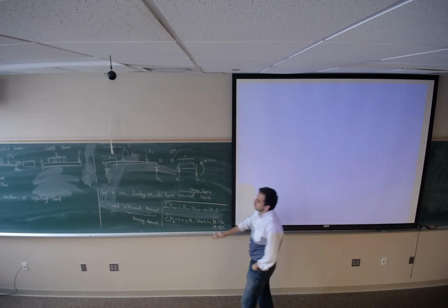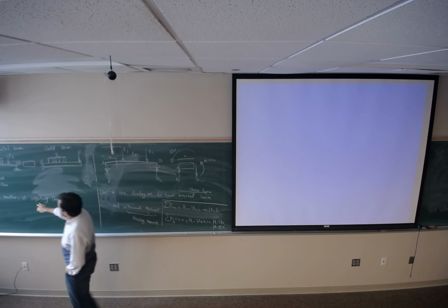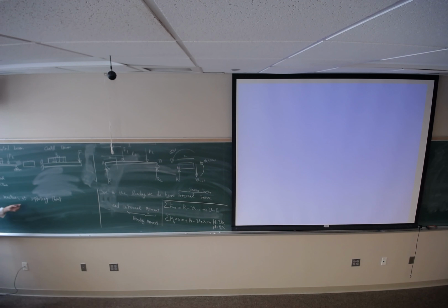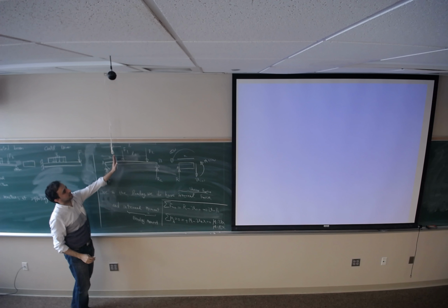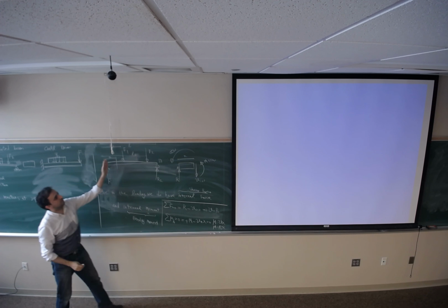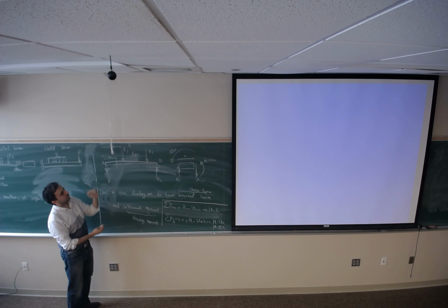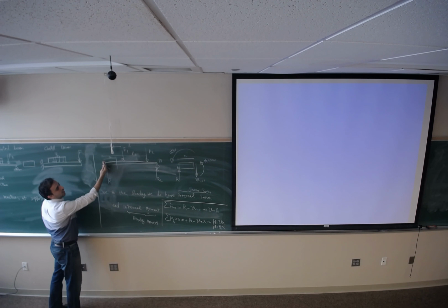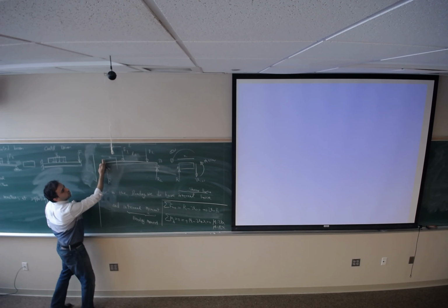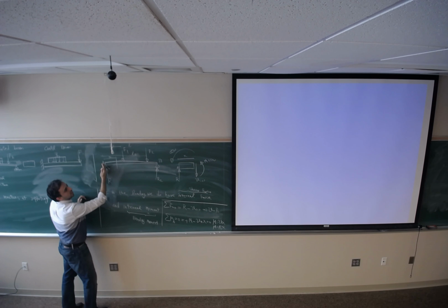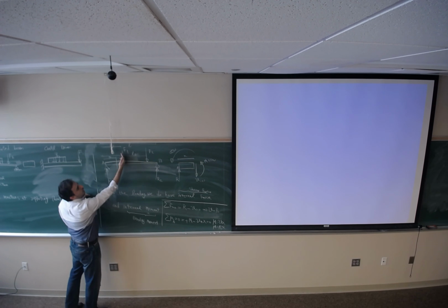So the first thing is to find the reactions at the supporting points. The second thing that we need to do is figure out how many sections we need to cut. How can I figure out the number of sections? You start from point A and move to the right side. From point A up to the first force that you see is going to be section 1.